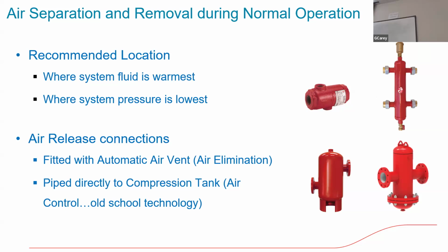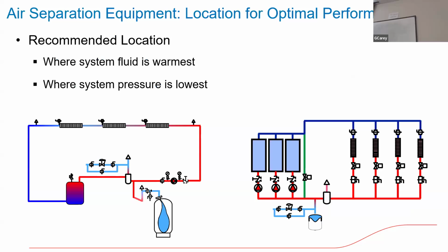And air release connections, everything that we're going to talk about and what you guys are going to see moving forward in your career will be this: air elimination. So there'll be some type of vent located on top of all of these air separating devices to discharge the air out.